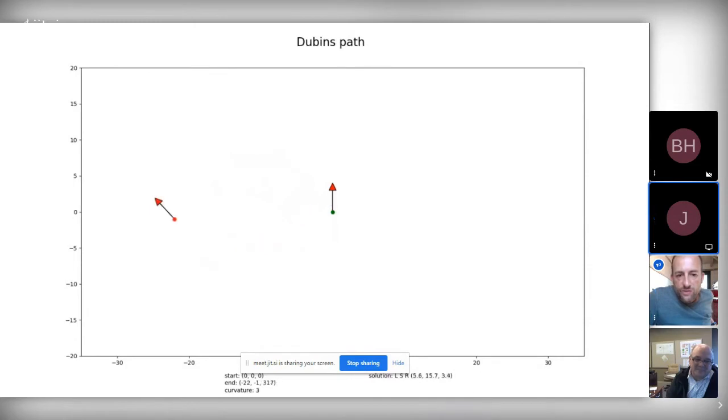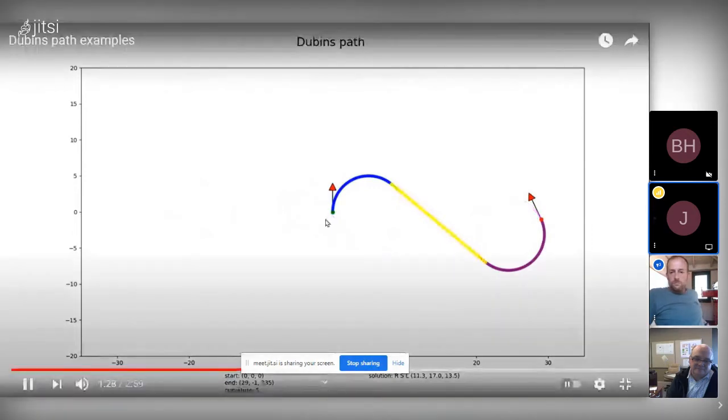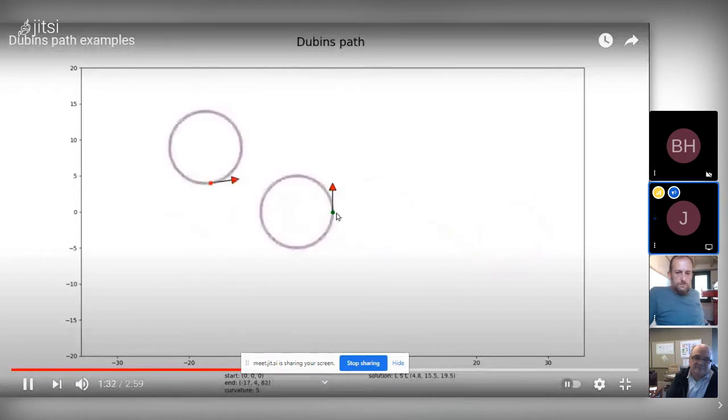If you go look at his description, it'll say look at Dubins, or if you look at the code for this, that points back to, I think, his website. It says Dubins works by defining 2 points. As this runs, the arrow shows the 2 points and what direction they're pointing. It draws a circle of a given radius on top of that, and then asks what's the shortest path? So it goes part way around the circle.